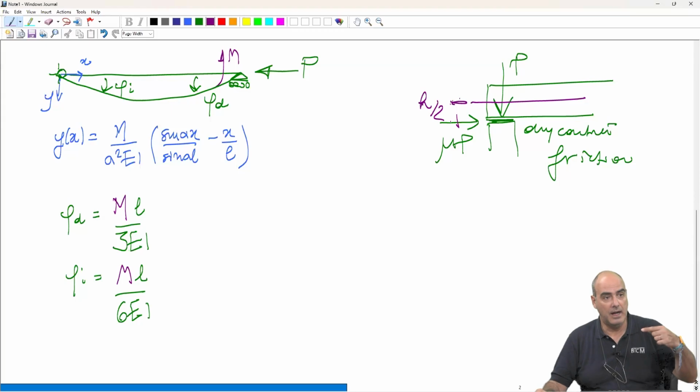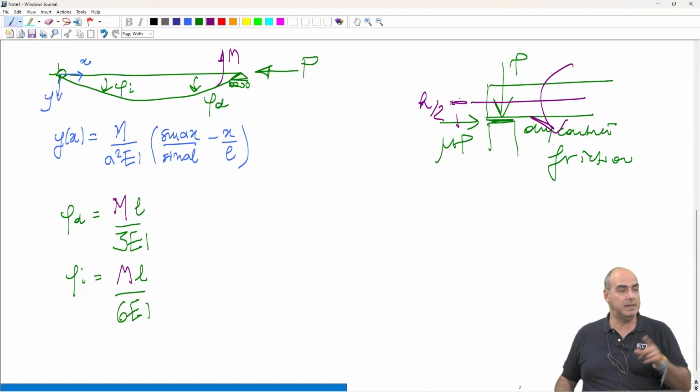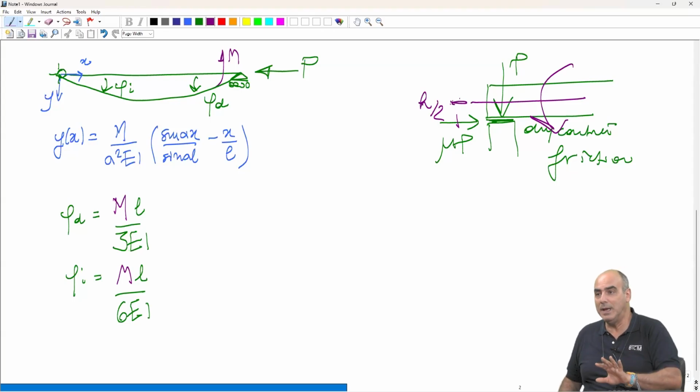So a force like that applied at the bottom of the beam means a bending moment like this, a negative bending moment. If you have not calculated it in your design, at least you will have cracking on the top.